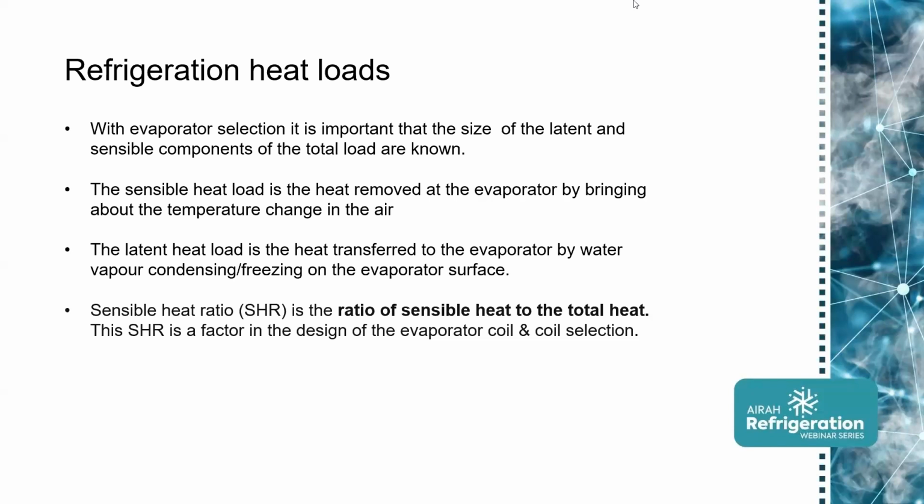And latent heat transfer is heat transfer involving phase change. So in this case, the sensible heat load is the heat removed at the evaporator by bringing about the temperature change in the air. You've got the warm air going in and you've got cold air coming out.